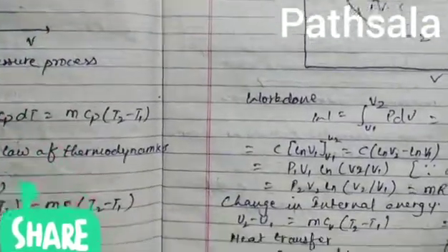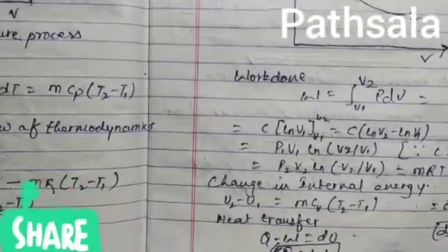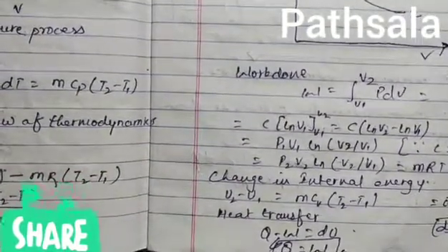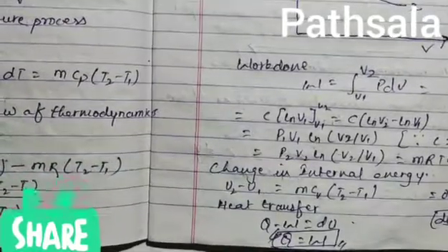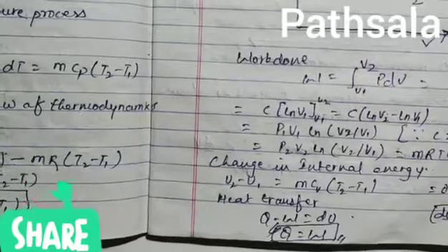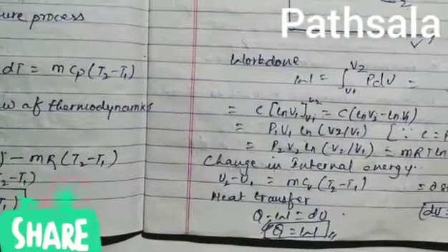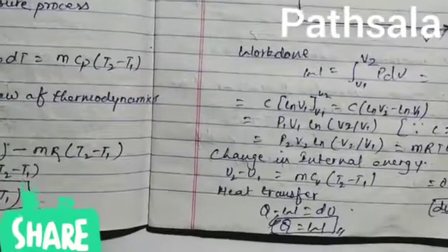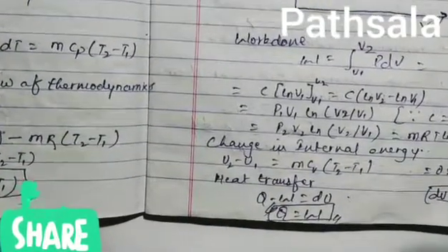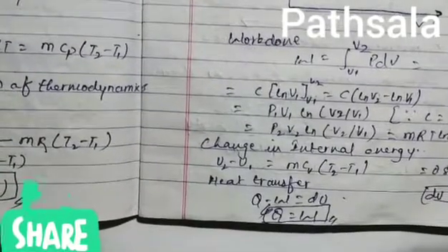Now we find the work done, which is equal to the integration of P dV from volume V1 to V2. Integrating, we get ln V1 to V2, so we get P1 V1 ln (V2 upon V1), which is the same as m R T ln (V2 upon V1).